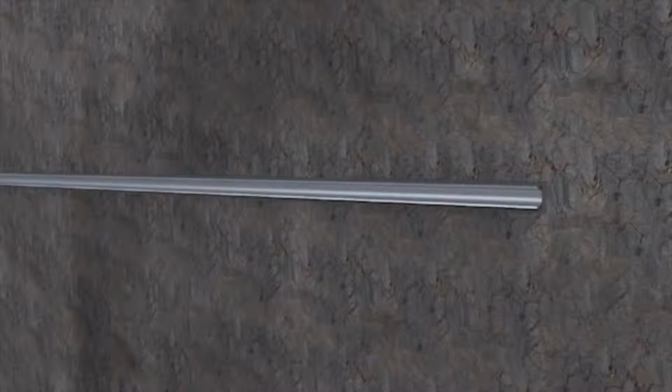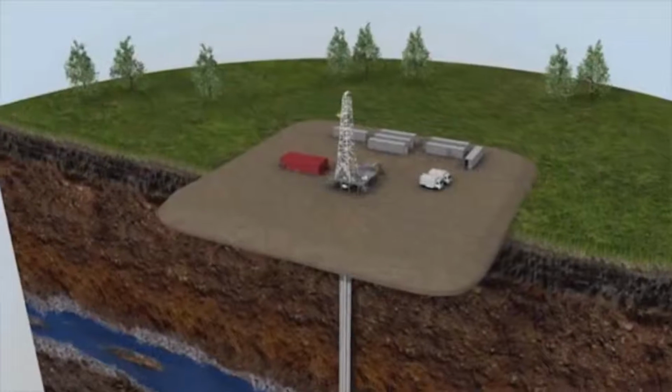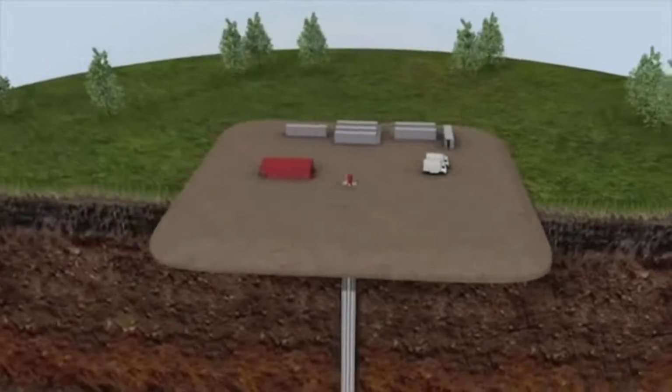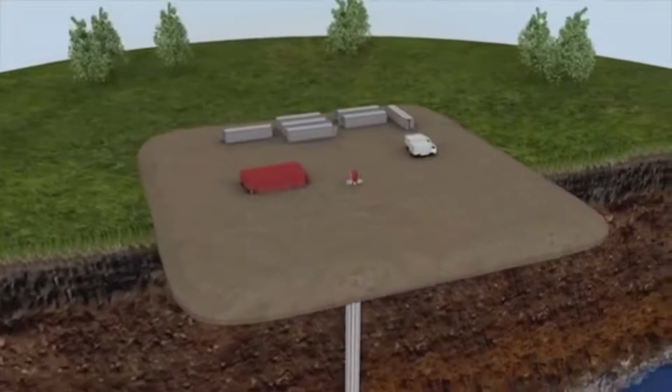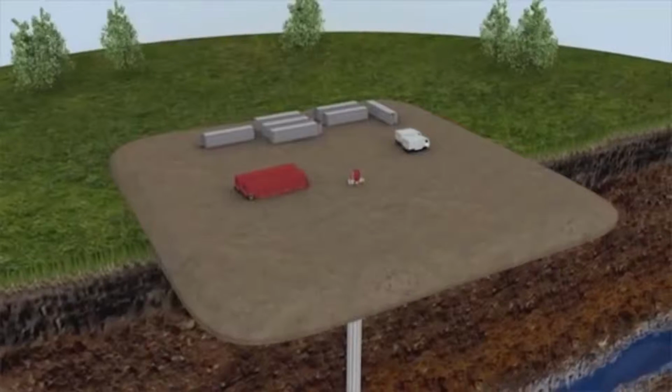When the targeted distance is reached, the drill pipe is removed and additional steel casing is inserted through the full length of the wellbore. Once again, the casing is cemented in place. For some horizontal developments, new technology in the form of sliding sleeves and mechanical isolation devices replaces cement in the creation of isolations along the wellbore. Once the drilling is finished and the final casing has been installed, the drilling rig is removed and preparations are made for the next steps, well completion.